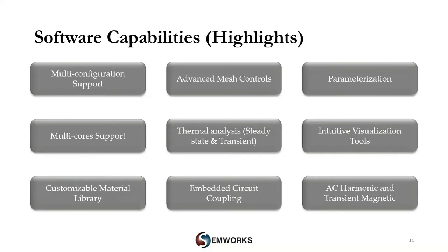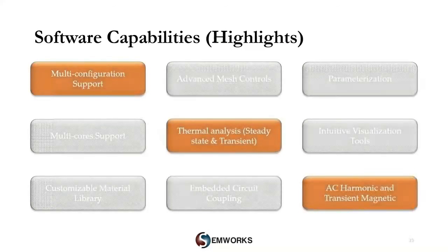Now this slide represents a small subset of capabilities available in our EMS software product. To simulate an induction heating problem, 3 capabilities are highlighted and utilized in the product demo you saw earlier. Number 1, multi-configuration support. This capability of SOLIDWORKS enables users to maintain multiple versions of a part or an assembly in a single file. The differences between configurations are established by changing dimension values, suppressing features, and changing other parameters.